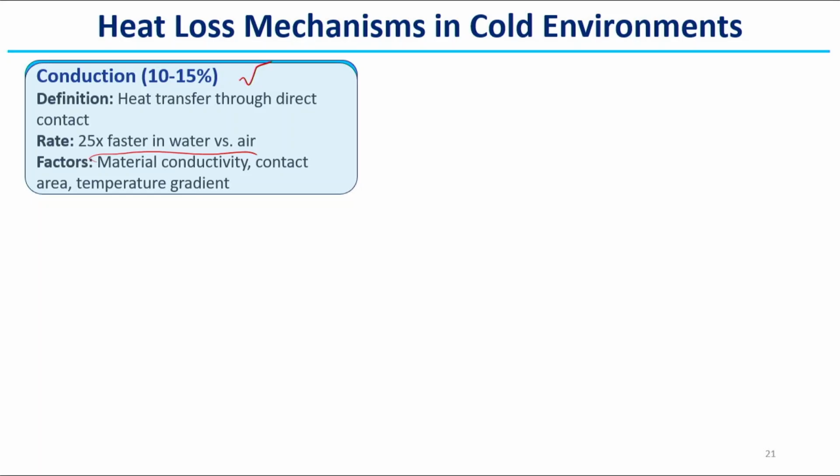In case of dry fabric with pores where air entrapment is there, that will prevent the heat loss due to conduction. But when wet, the water is taking the space of the air, so the conductive heat loss will be much faster.